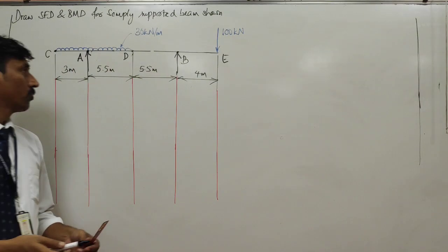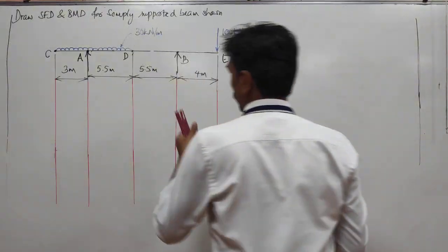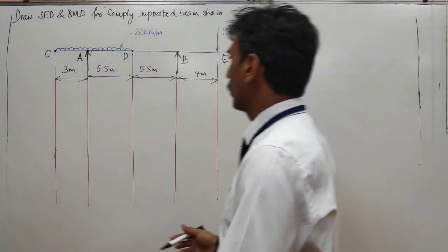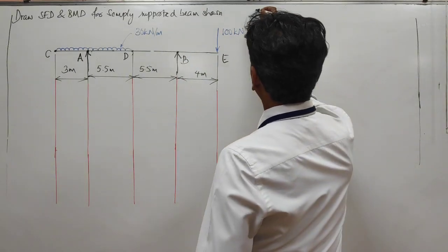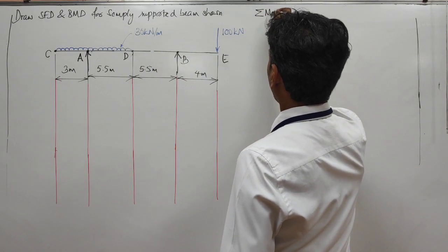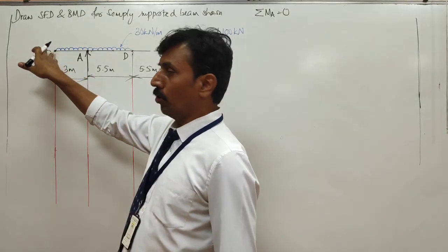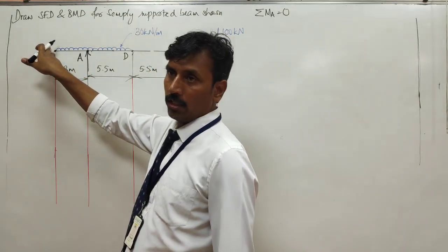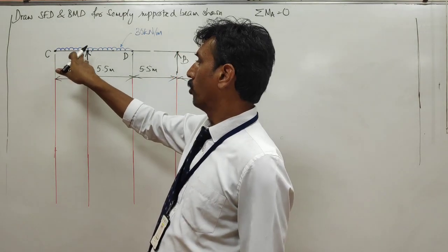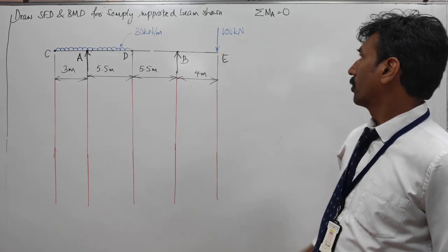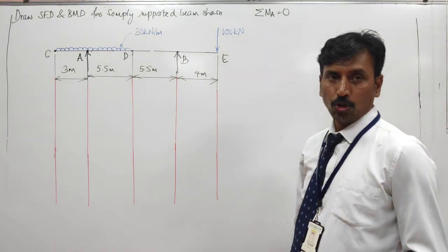Okay, now to find out the reactions at A and B, which are the supports, as usual, let us take moment about A. So usually we would take the last point, which is the support, but don't take about C. Usually you should actually take about a point where the reaction forces are not known to you. So reaction force at A is not known to you.